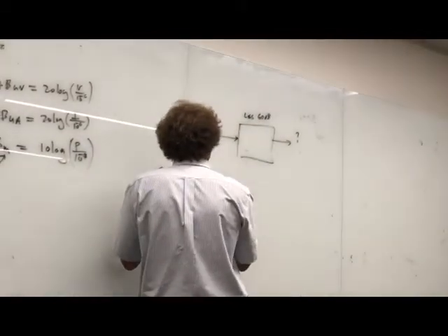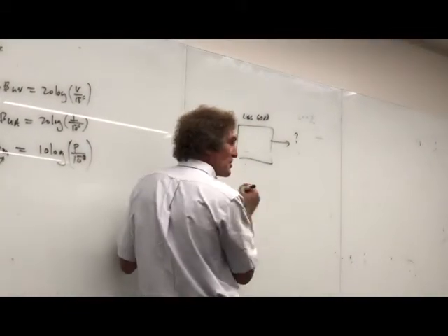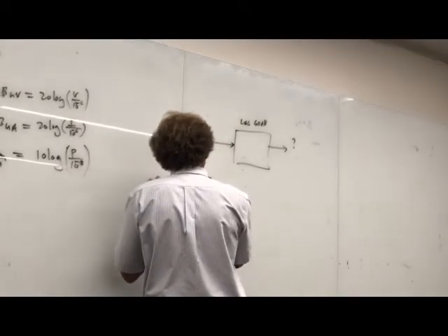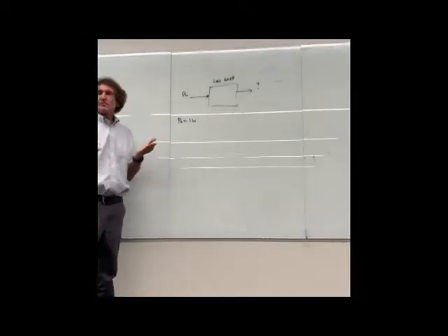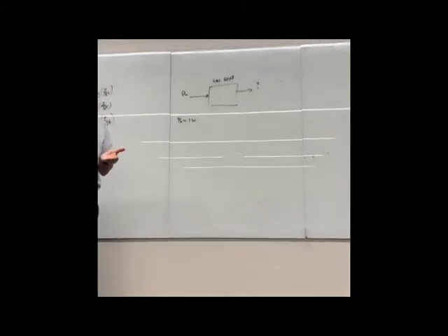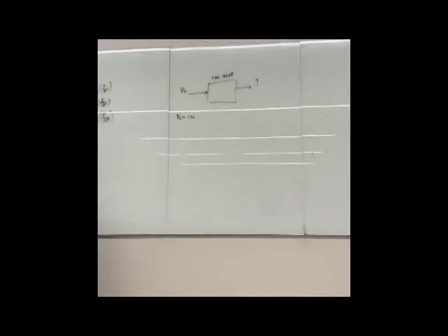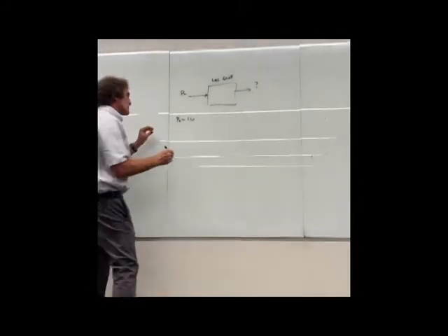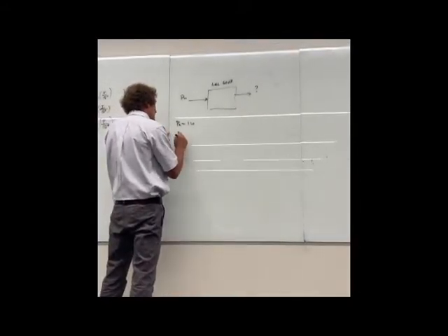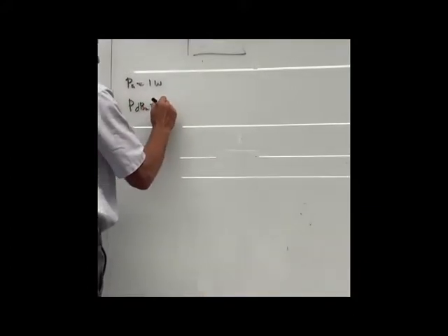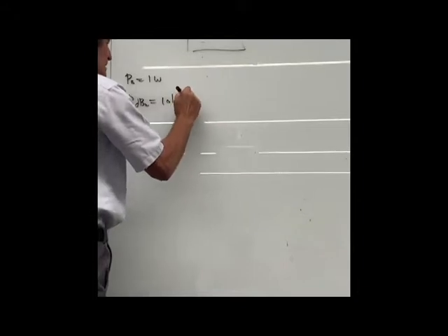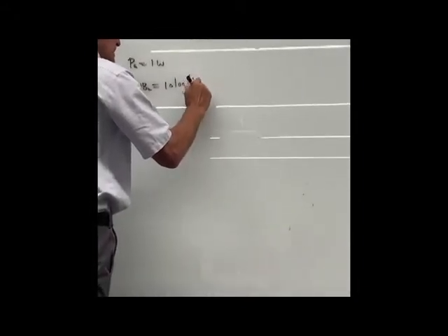We're starting with a very common thing. Suppose I put in a power input of 1 watt. Everybody appreciates 1 watt is a simple number, right? So what is 1 watt in terms of dBm? I'm going to put power now in terms of dBm. That would be 10 times the log of 1 over 10 to the minus third.